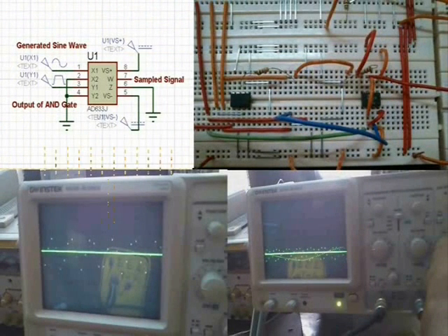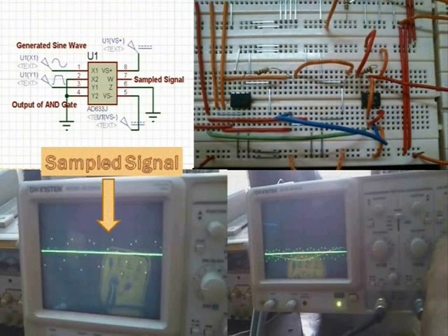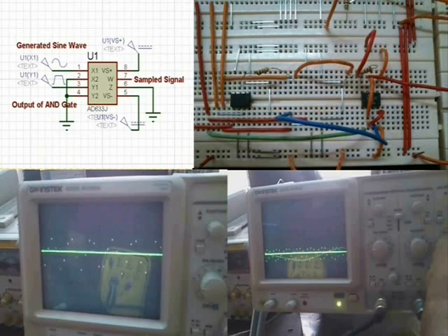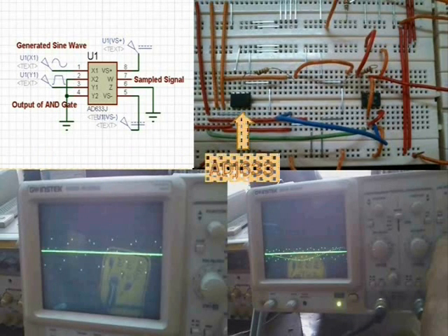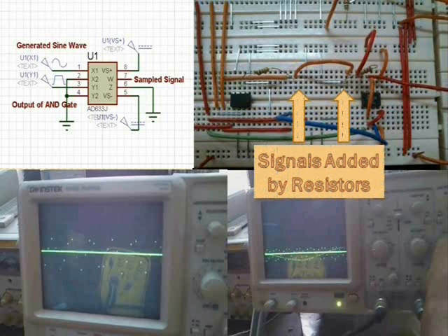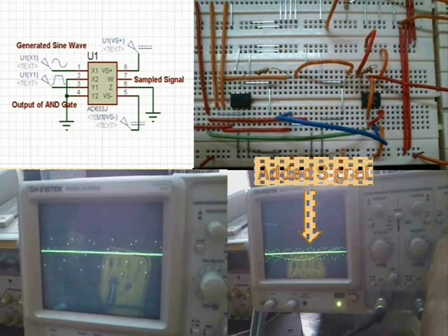The major part of transmitting is sampling a sine wave with one of the shifted clocks. Firstly, it was thought to be done with a MOSFET or BJT, but finally it was done with the AD633 IC, which does an excellent job. At the end of the transmitter part, we have added the outputs of two AD633 ICs through resistors of 1K, and luckily the transmitting part is over.